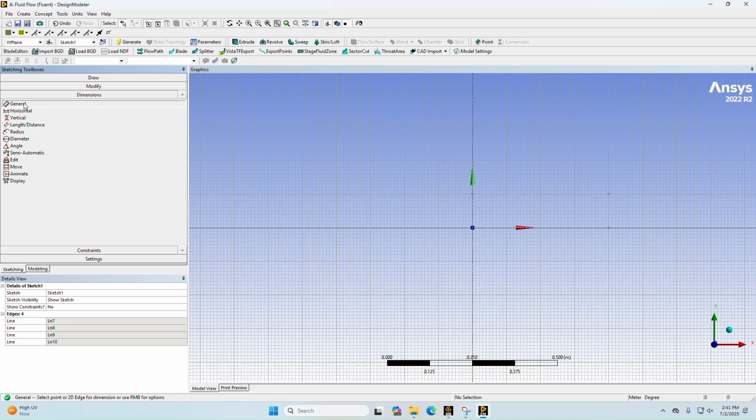So we'll hit here, boom, boom, for our vertical and horizontal. So this bottom portion will represent the plate, the flat plate that we'll be using. This will be a boundary, and this will be another boundary for the air that will be moving over this plate, and then this will be the top boundary.